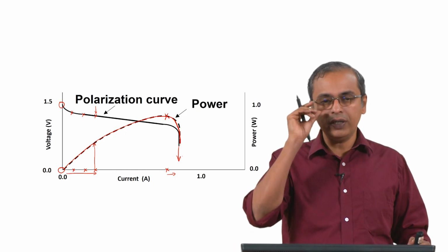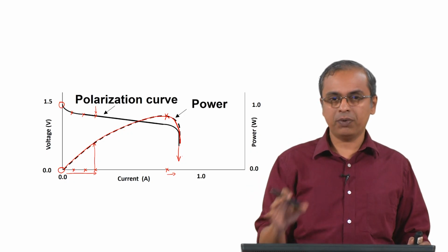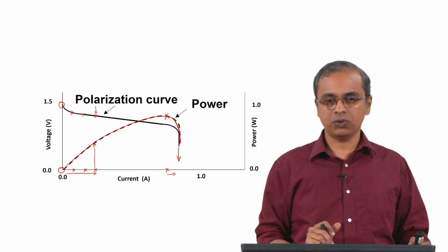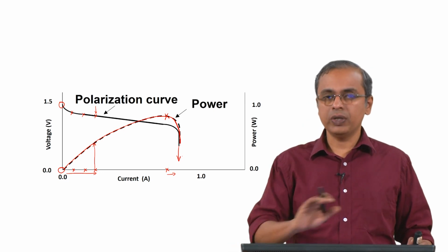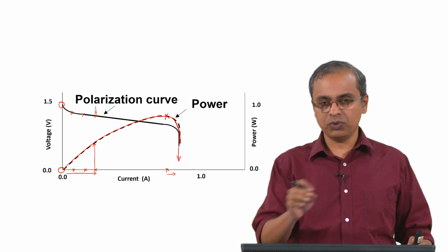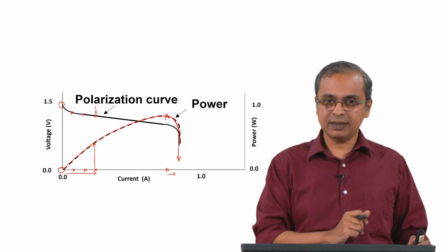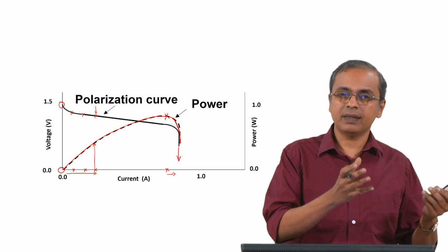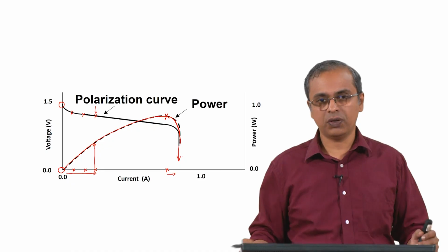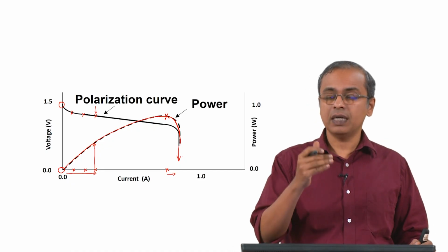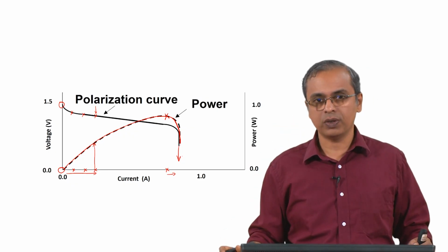So, if you are doing a project and you really know what you are doing, you have some number of devices that need to be powered by a power source. You need to figure out how much power those devices require, the total power required by the devices in your circuit. When you buy a power source for that circuit, that power source should have a maximum power that is distinctly higher than the maximum power you are going to draw.